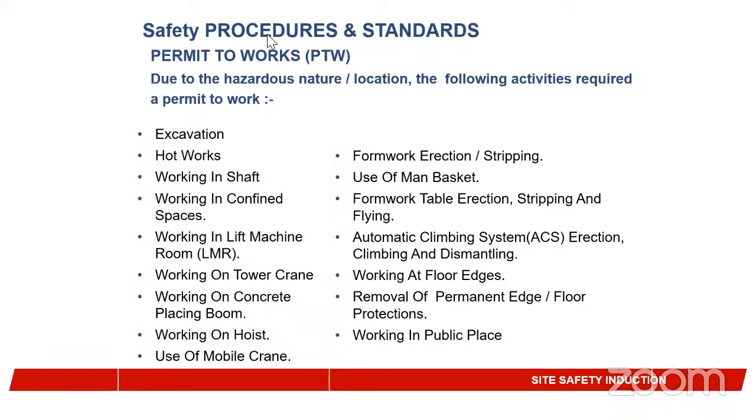Excavation, earthwork, working in shaft. You tell them these jobs require a permit to work. When you are doing this job, please request your permit. In fact, before you do any work, ask your supervisor, sir, where is the permit for this job? It's part of the safety induction you should give the workers. For various activities, you need a permit to work at all times: for earthwork, watertight excavation, working at floor edges, removal of permanent edges, working in public space. Based on the work you're doing, they need the permit to work that addresses that particular job.